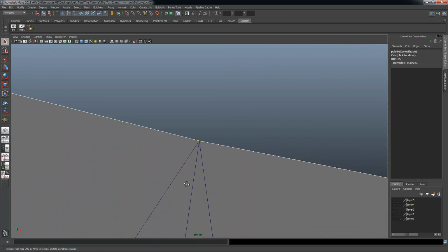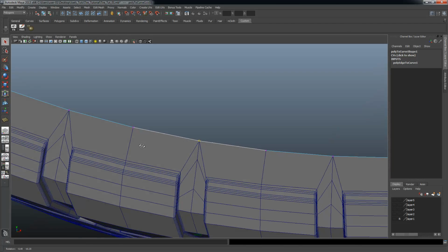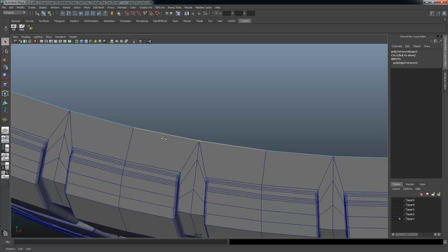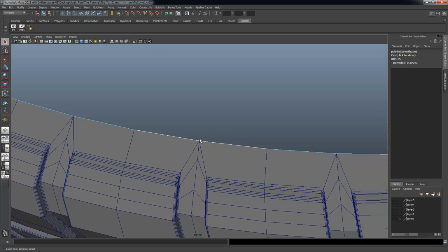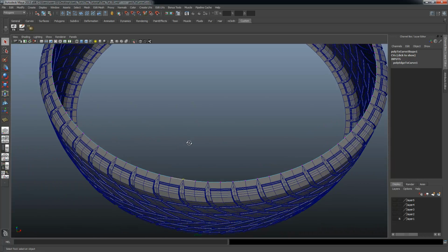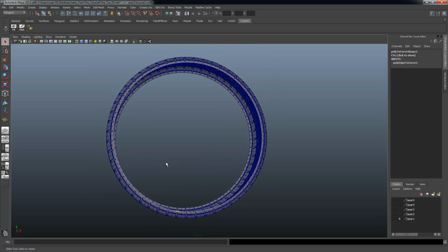this line begins and ends, because by default this line cannot be open, and it's probably not a good idea for me to close it either. So that's where the line starts and ends, and I want to remember that, because when I build my surface, I'm going to have to weld those vertices there across. So I just want to remember that position.